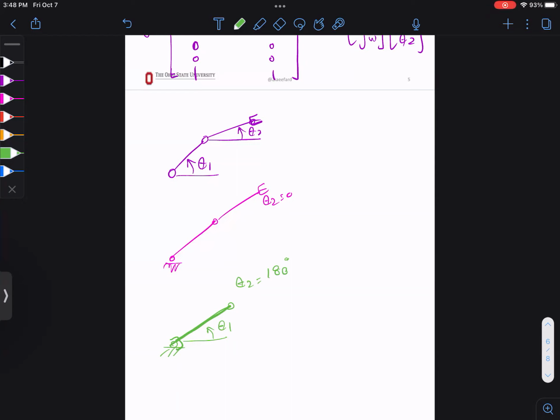So let's take this joint, right? This arm can move, right? Look at the orientation of the end effector. If this is 0 and these two are aligned, then when I rotate, the motors are working, but nothing is actually happening. This is because of this alignment, this position.